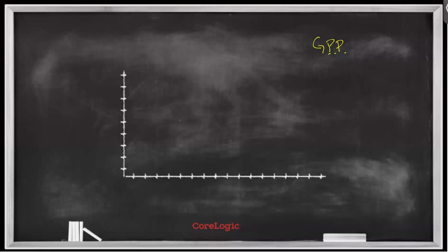Because you're missing things that it's relative to, right? Relative humidity. So for that reason, we don't use relative humidity to understand humidity control. We use the humidity ratio, or grains per pound. Now, when I make this assessment of my humidity for humidity control, just using some really generic examples, we're going